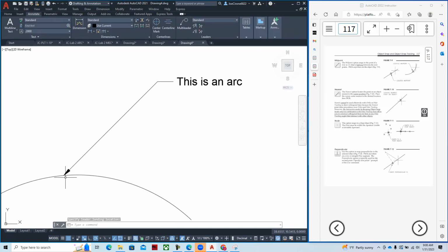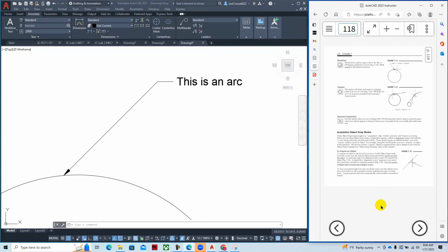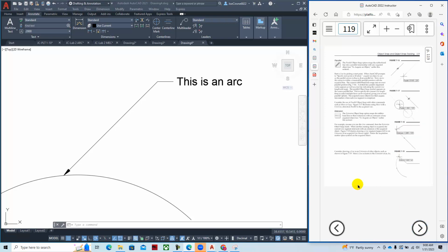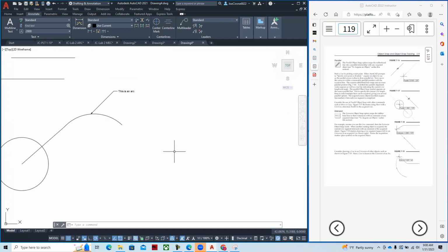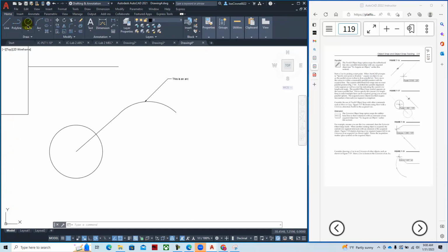And so it's very precise for us to be able to work with object snaps and draw commands. And again, showing you how to work from an endpoint, making lines tangent, and being able to make lines parallel. And so if we had a couple of circles, we can erase this. And I wanted to draw a line tangent and tangent.